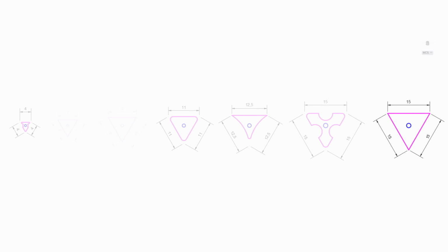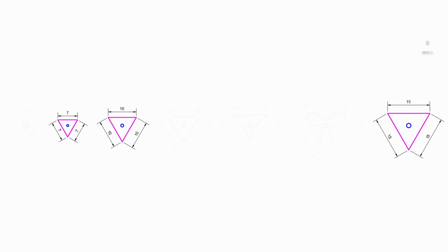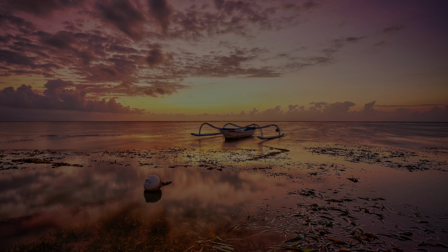The smallest tool is 4 mm equilateral side length, and the largest one is 15 mm long. As we can see, tools number 1, 4, 5, and 6 are non-ideal tool shapes, and tools number 2, 3, and 7 are ideal tool shapes. After all tools have been created in CAD software and saved in a DXF for each tool, the next step is to import all the tools into Image2Punch.